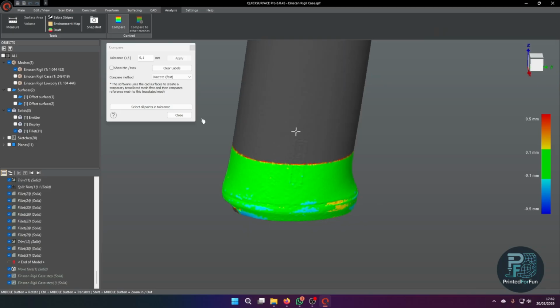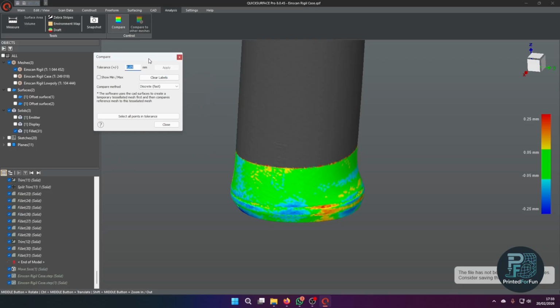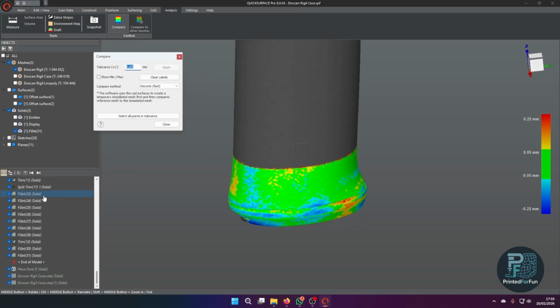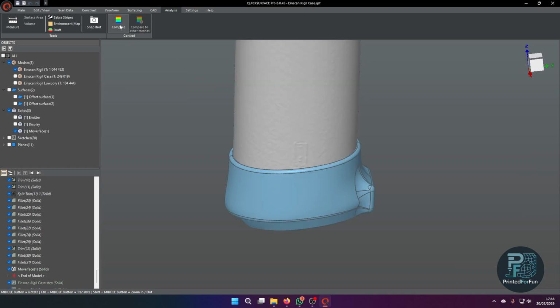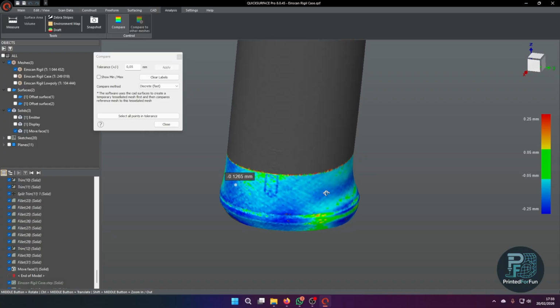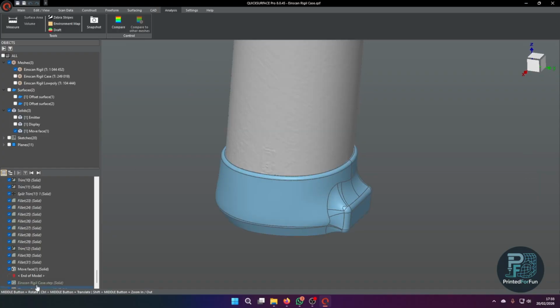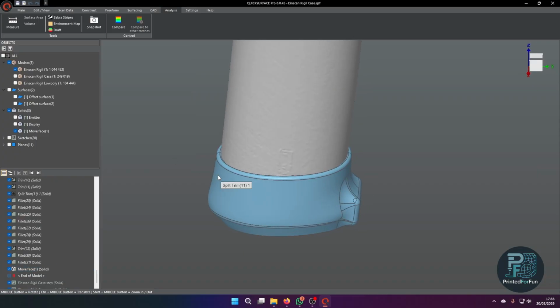So if you can look now, this is the current state. So let's do it to 0.05 millimeters. You can see I'm basically spot on. And now I move the surface, and let's do it again. And as you can see, I'm now down roughly 0.125 millimeters, I think, or 0.1 millimeter. So this created the nice friction that's needed to hold it on and for it not to move around.